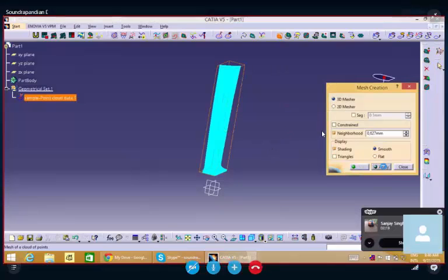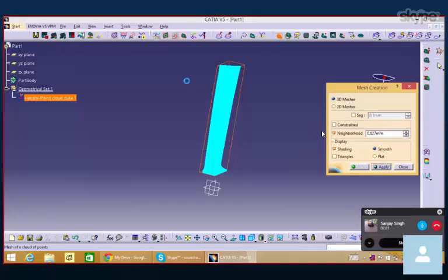So first we are doing the 3D mesh. Here we don't have any problem with our point cloud data, so we can directly go for 3D mesh. Suppose we can't retain our shape, like that car door, then at that time we have to go for a filter, and then go for meshing. Okay, okay.